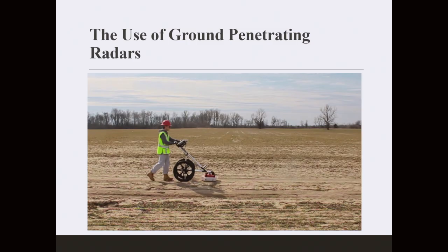Bear in mind, the higher the frequency, the better the resolution. However, you cannot use higher frequency for big depth. So if you are talking about a couple meters below the ground, like for pavement application, you can use as high frequency as you want. But if you are talking about piles, like drilling piles, depends on how deep the pile would go, 15, 20, 25 meters, the deeper you go, the lower the frequency that should be used, right? But it comes at a cost where the accuracy goes down.